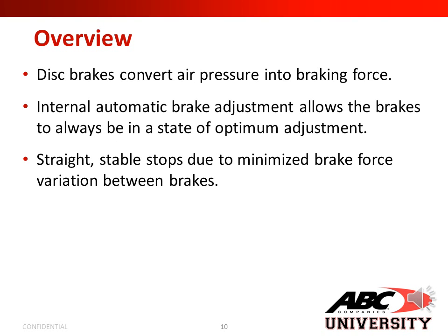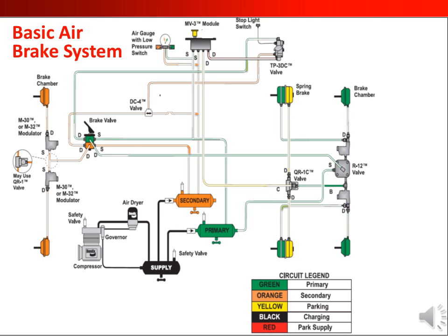Disc brakes convert air pressure into braking force. Internal automatic brake adjustment allows the brakes to always be in a state of optimum adjustment. Straight, stable stops due to minimized brake force variations between the brakes. In this slide, this is a basic air brake system. In this slide, we're going to show you how a general system actually gets pressurized with the air.